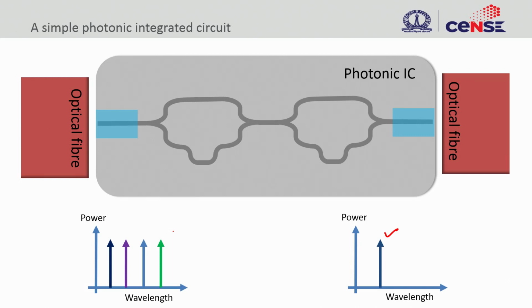What we can conclude here is we have gone from a block diagram, started with a coupler design, looked at what kind of waveguide we want, and also what strategy we can use to create this wavelength selective filtering of one single channel out of 4. This is how you go about realizing any application.